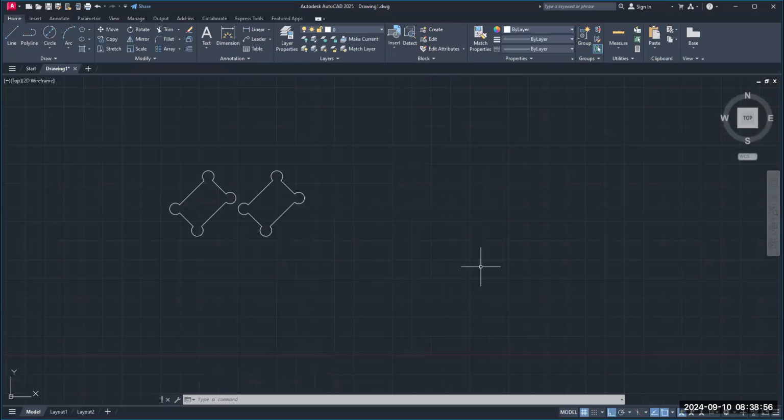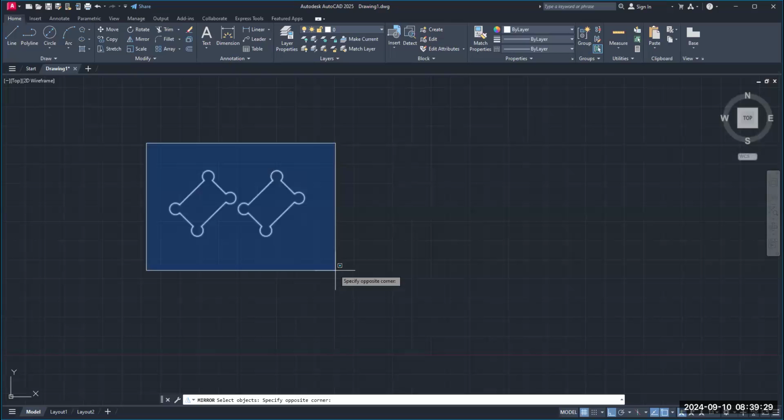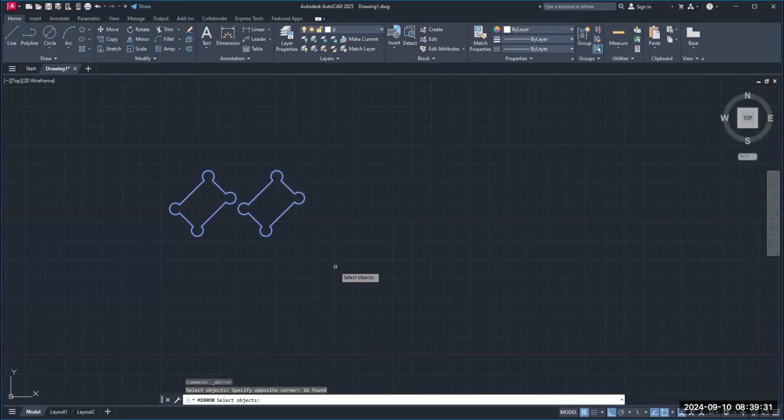We've been working with that up to this point already. Now what I want to do is show you how to mirror something. All right, so this is the command mirror, and let's have some fun with this. So if we go here and we click on mirror, now down here at the bottom it says select the objects you want to mirror. I want you to click and window around all of this. Click. And then I want you to enter.